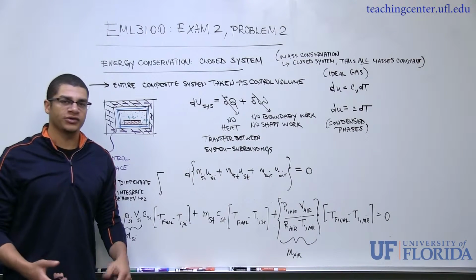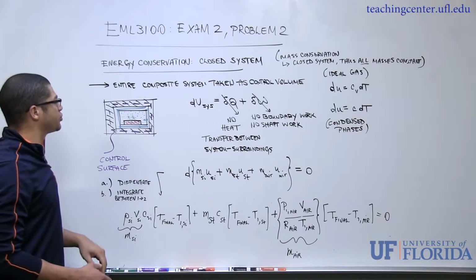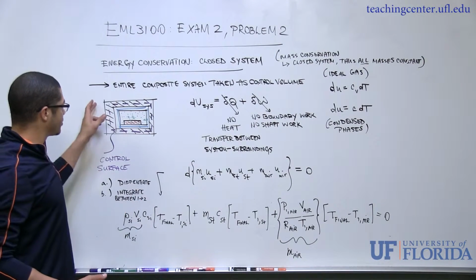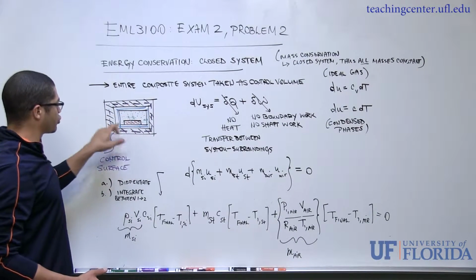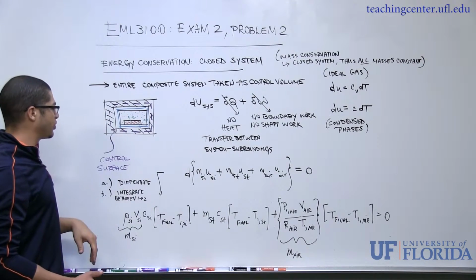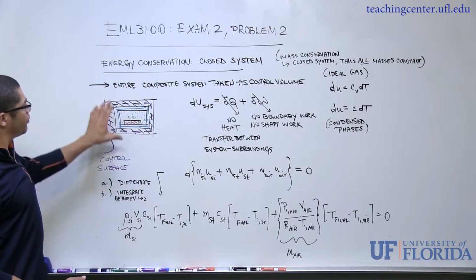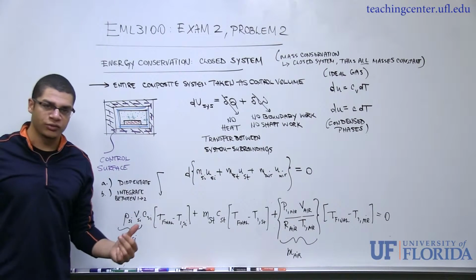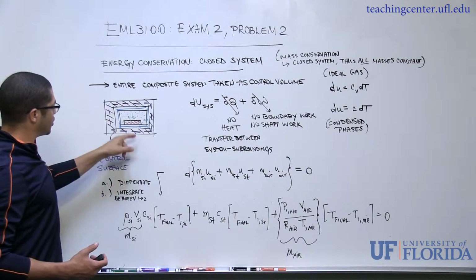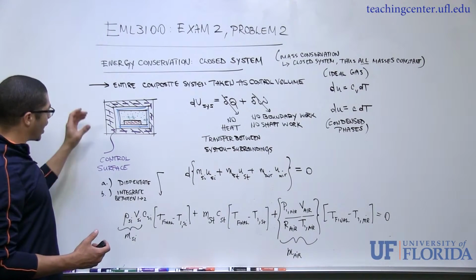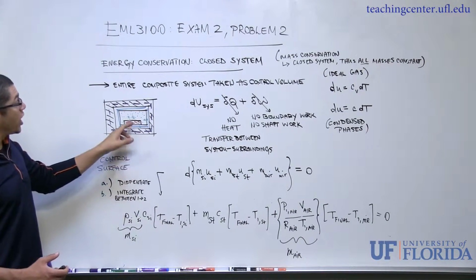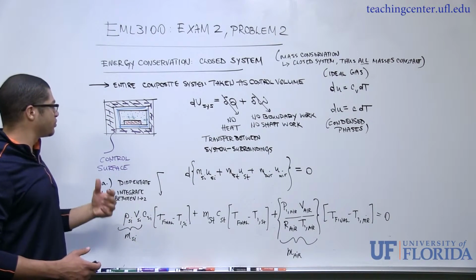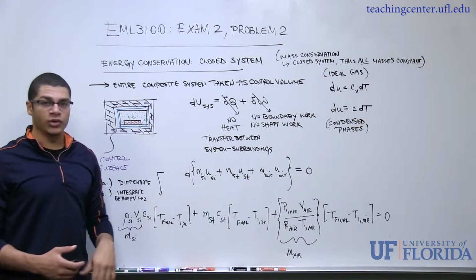Moving forward with the analysis, we will apply the energy conservation principle, or the first law of thermodynamics, for our closed system, which consists of the insulation, the steel outer structure, the silicon wafer, and the air contained inside. Here, I've drawn a purple dashed line that cuts through the insulation, to show what exactly we're analyzing. Note that no arrows cross this boundary, so there's no energetic interaction, or heat transfer, between the system and surroundings.